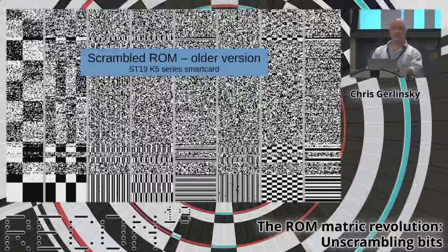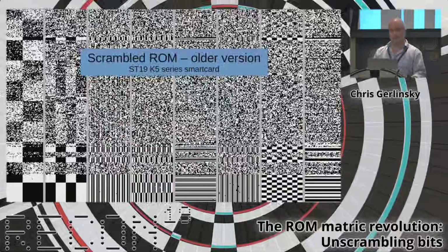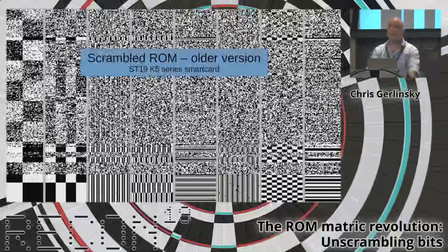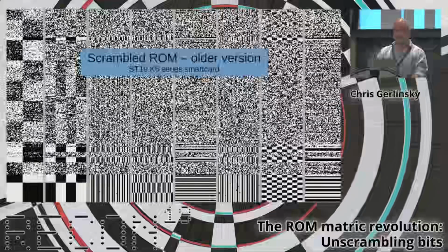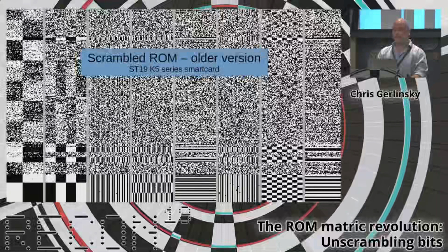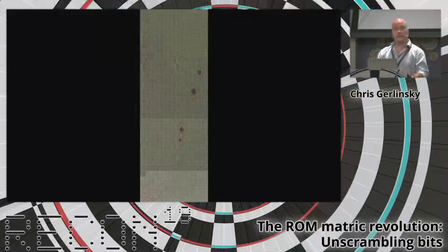If we look at the decrypted version of this ROM, all the really black and white checkerboard areas actually decrypted perfectly to 0. Those were just empty spaces, and then we have code in the rest of the space. Being able to visually see these patterns is the whole basis of how I'm descrambling these ROMs. There tend to be these visual patterns that show through, because of the simplicity of the scrambling methods, which again don't take any time for decryption and so on.